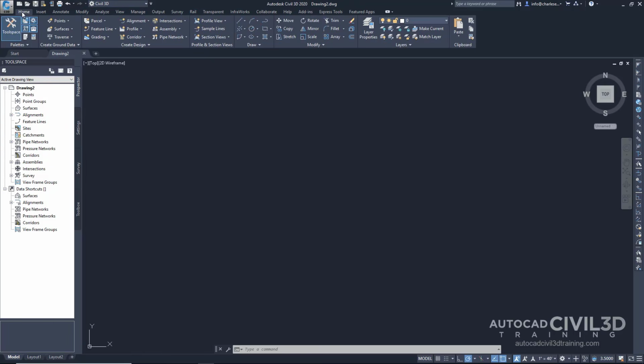So what I'd like to do is swap out this workspace list with my layers list. The reason being is that I know that this list is actually down here at the bottom as well. If I click on this cog, we've got the list right here. So the way that I do that is I right click on this and then click remove from quick access toolbar.